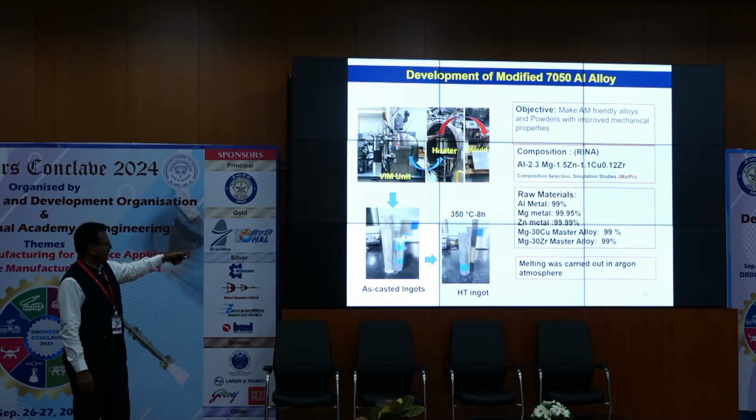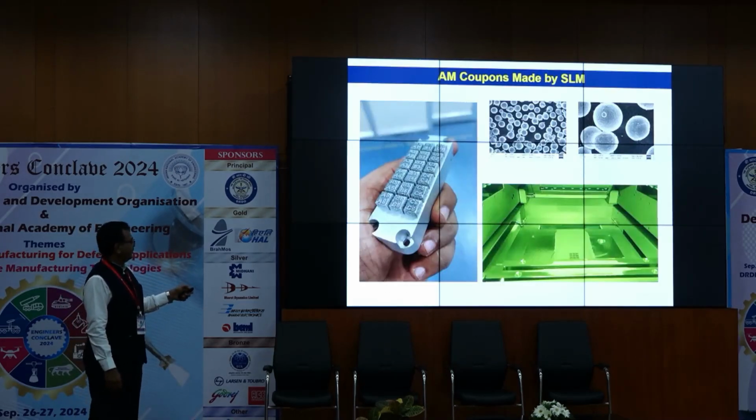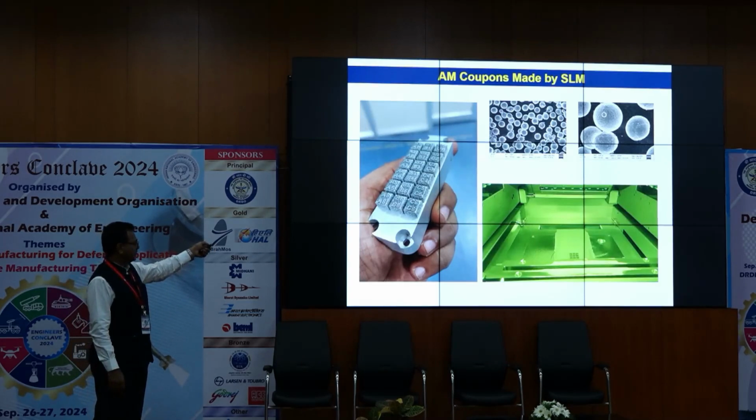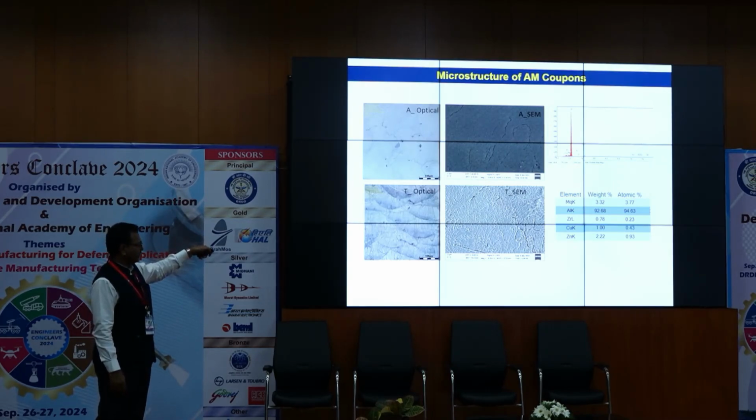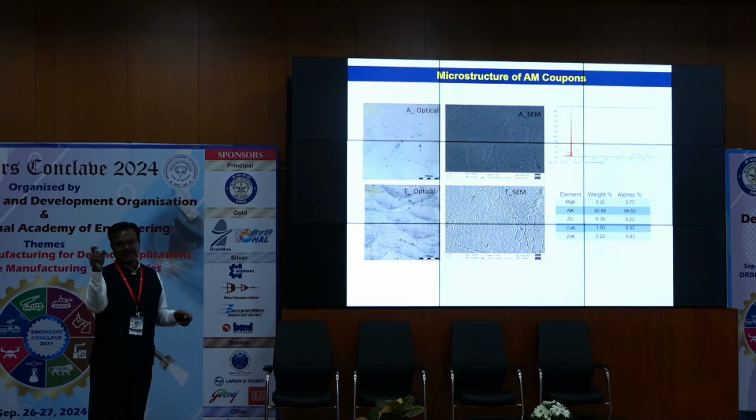Then we made the ingots using our vacuum induction melting. Then we produced the powders. Then we printed it using our SLM machine. We were not able to completely avoid the cracks; there are still some micro cracks. Still, work is going on so that we can tweak those.